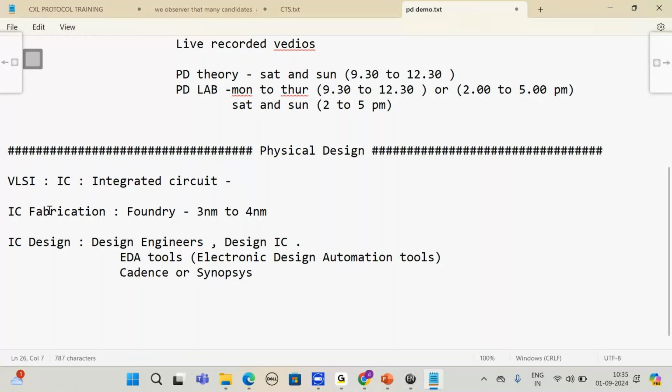So here, the IC design team is going to give the fabrication team a file called the GDS2 file. This GDS2 file is given to the Foundry. Based on this, your Foundry is going to fabricate the IC for you. Then what is the content of this GDS2 file?